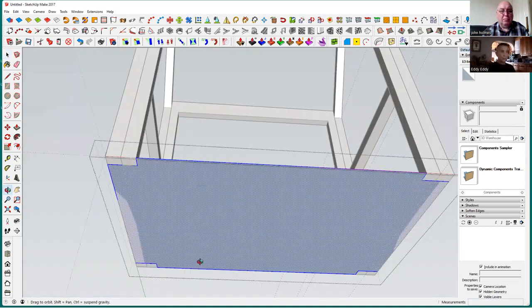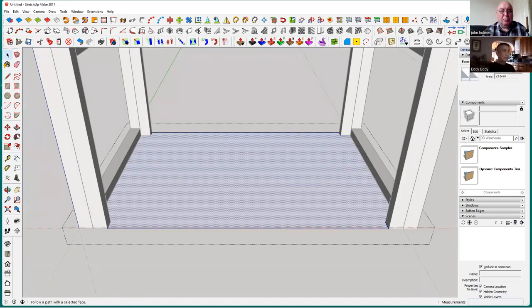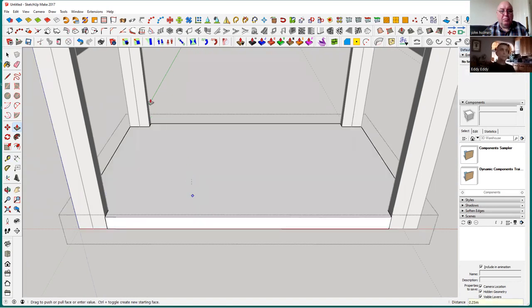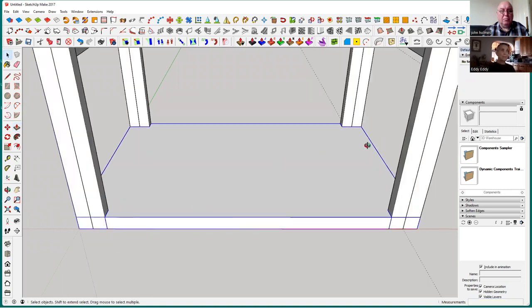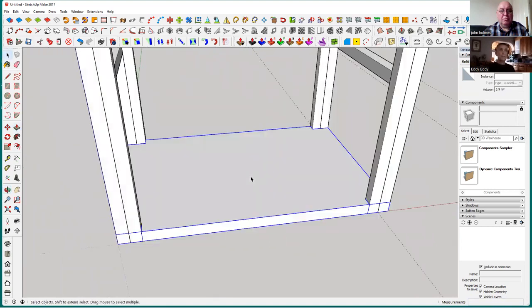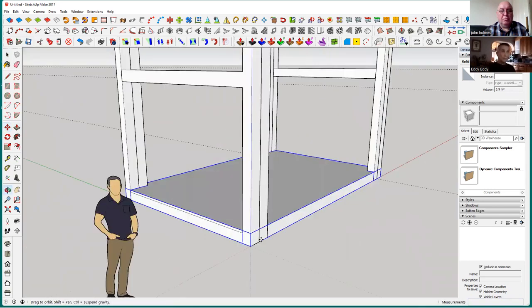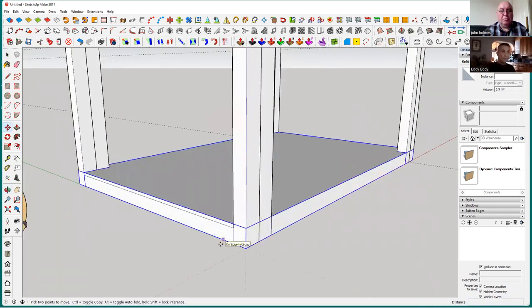So what you should do is turn it back up, push pull tool, pull it up 0.25 millimeters. Click away from it, and now we've got our floor, and then we've got to move the floor up, move tool, click on the bottom there, and the up arrow, so go straight up in the air.